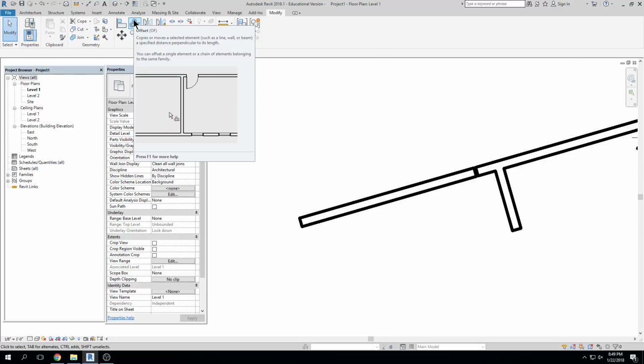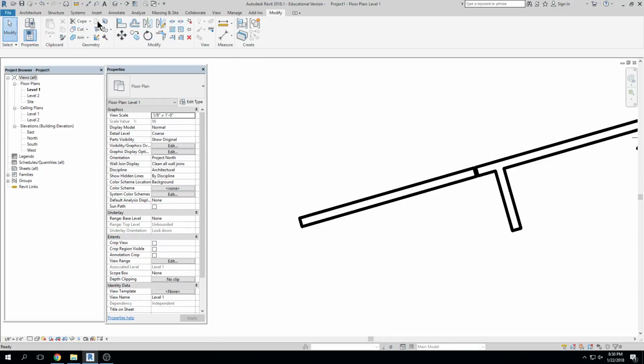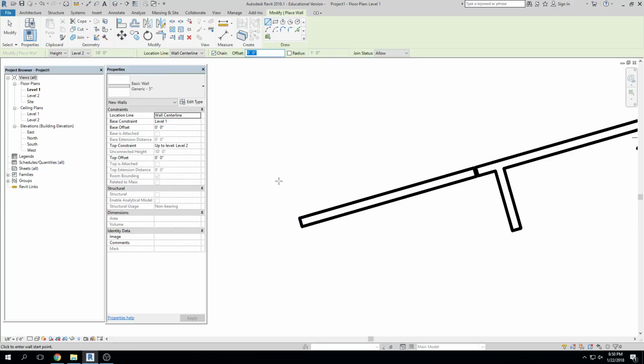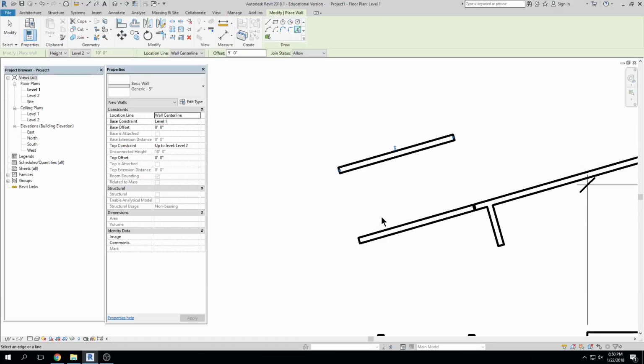Why would we use offset versus the thing we used last time where we pick? Oh, it's the same. It's kind of the same thing. Yeah. So Shantae is saying, well, why would I use offset when I can go to architecture wall and I can add an offset here, right? Like 5 foot, enter, and I can use my pick tool, click, and do that. So we did that last time. Yeah, it's the exact same thing. That's an offset. It's just an offset within the wall command.